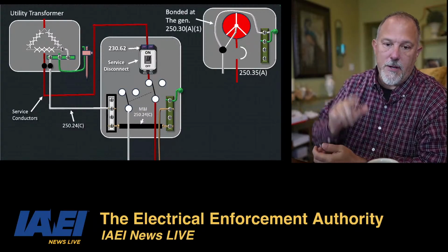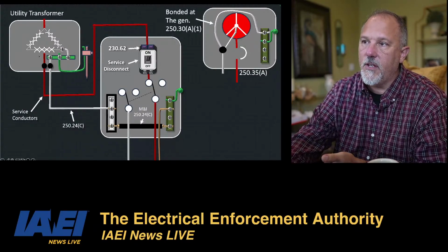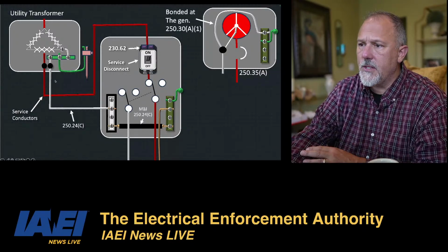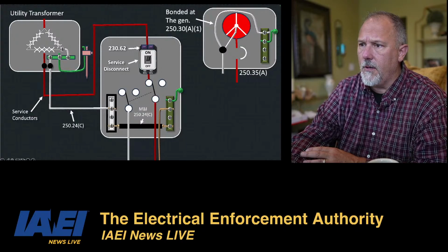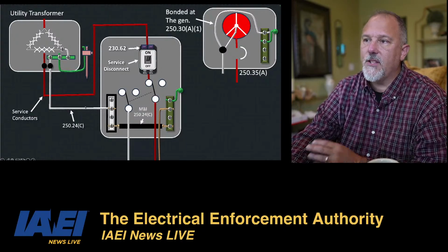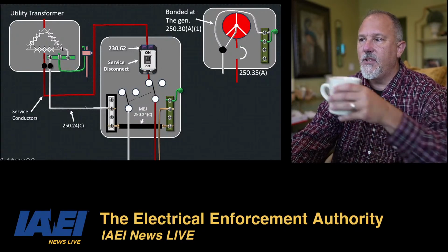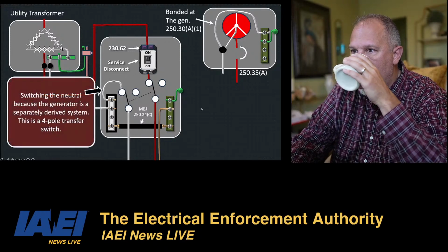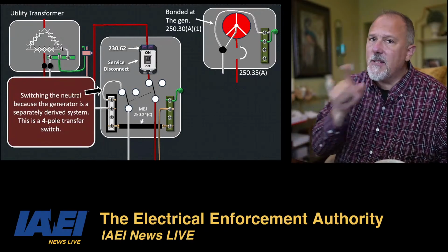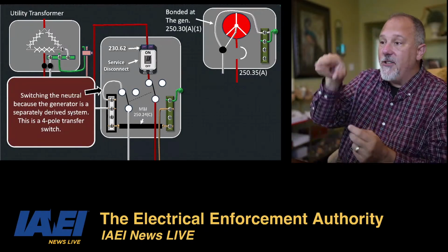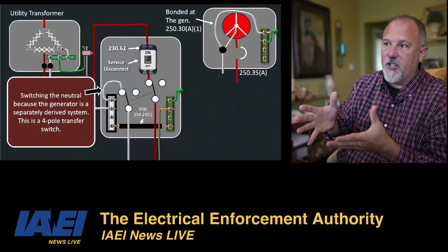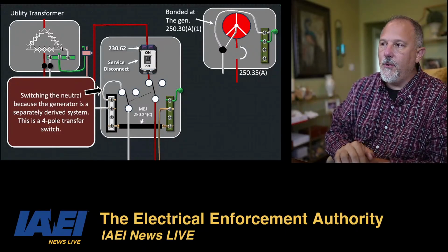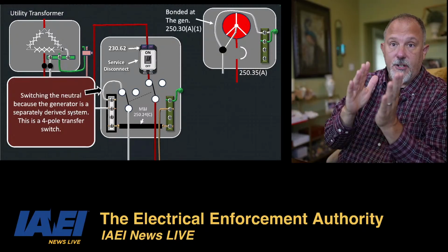You'll notice it's bonded over there in the transformer. It's bonded in here, and all of that is grounded. So I bring that equipment over. I bring my 3, and that's what's going to connect my 2 together. All right. So then, because I'm going to switch the neutral, my neutral is really all bonded at this point. So I'm going to come off of that neutral bar, and I'm going to go straight into a disconnect, a transfer, right?